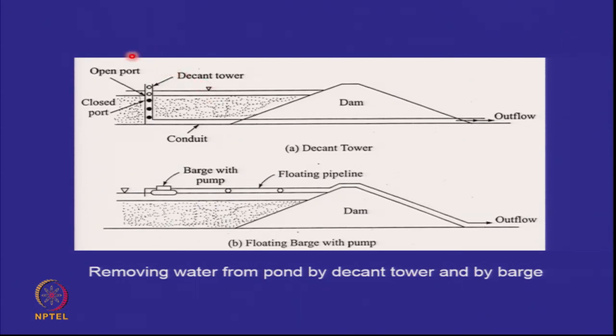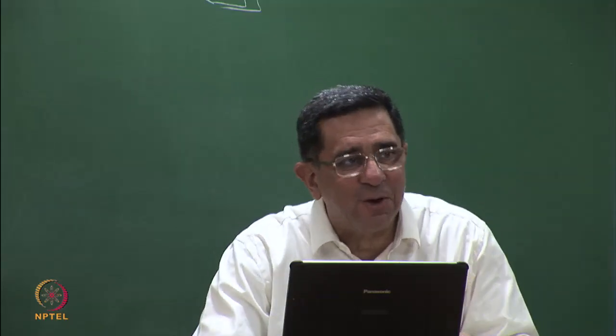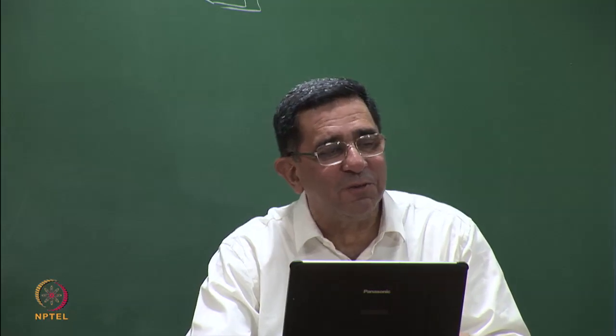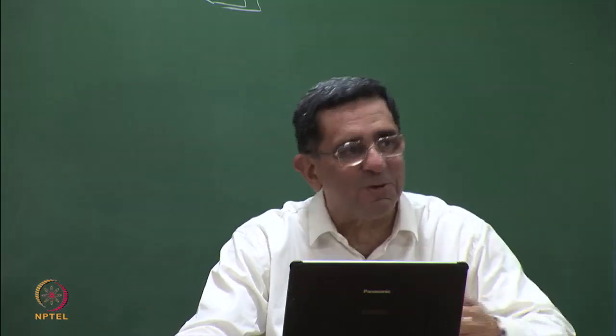When the third embankment is made, what will happen? It will sit on top of the well. So your well has to be sufficiently back in your design. If you are going to have 6 raisings, you can't have a well which comes under the footprint of the perimeter embankment after the second raising. And that was something also which was developed from time to time as we went along.